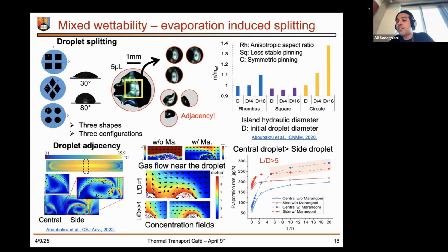But again, the design of the surface, I don't know, to be honest. Whether we need smaller spots or larger spots, or what kind of wettability gradient we expect for low temperature and wetting. But for wetting liquids, what I can suggest is that smaller islands provide better performance, because in this case it is not all about the stability of the evaporating liquid film. It is more about the activity of the boiling.